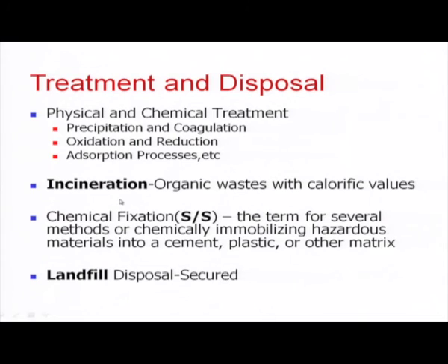So, in short, if you ask how hazardous waste is disposed, there are two main ways: one is incineration, the other one is landfill. We can make a comparison. Suppose a human being dies, the body is managed in two ways, either we go for burial or incinerate it. In the same way the hazardous waste, how we treat the dead body, same way it should be treated. If it is an organic one, go for incinerating it. If it is an inorganic one, stabilize it and put it into the native form. Okay. So, this is the one of a landfill.